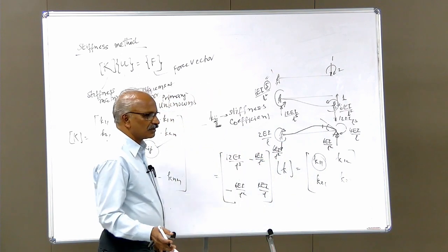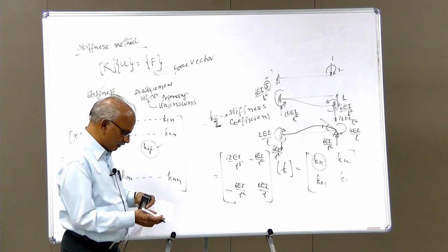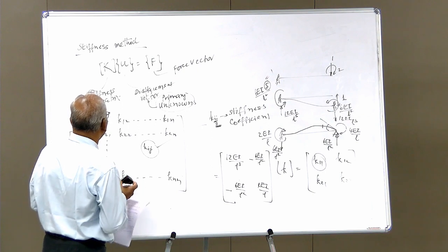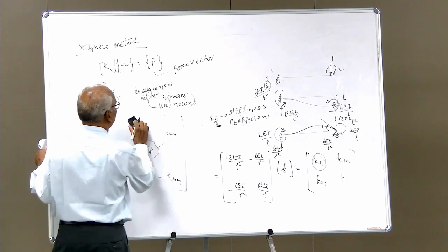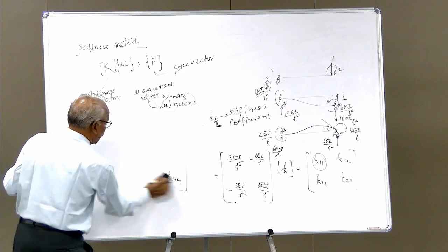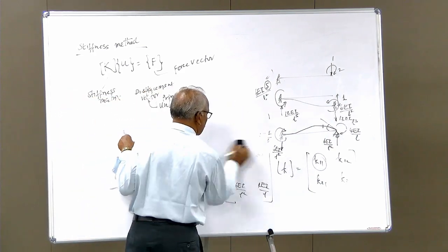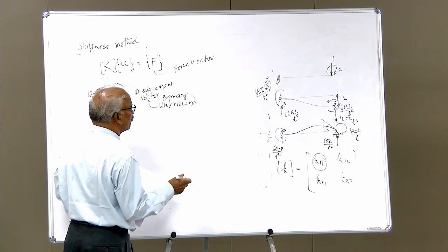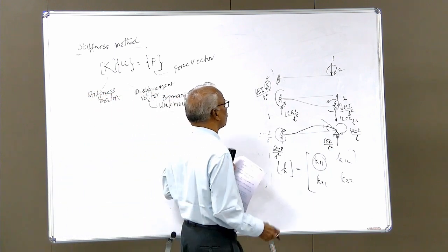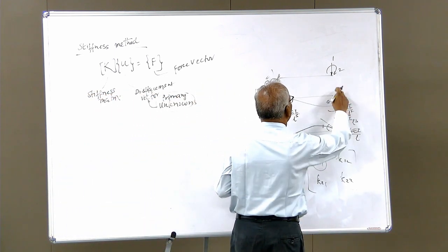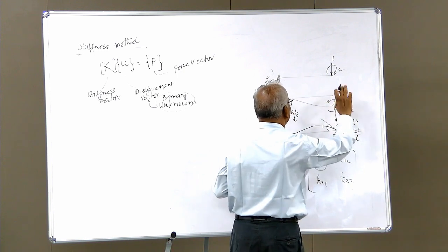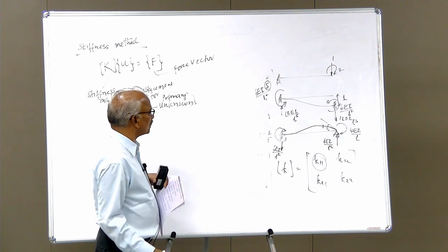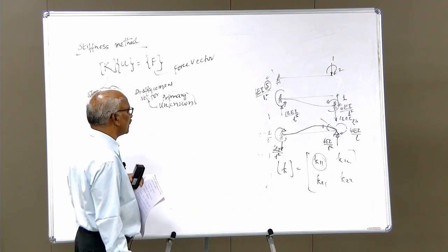So again, you are expected to be strong in the fundamentals. So that's about the stiffness matrix and also the equilibrium method. So this is sufficient for the introduction part. We are going to discuss everything elaborately. Now, here you have followed the superposition of displacements. You have applied displacement along coordinate 1 only, displacement along coordinate 2 only. So you apply one displacement at a time, and so this is also applicable only for linear and elastic structures.